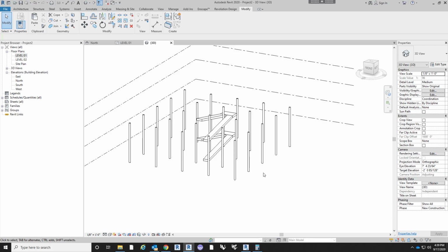If you change the bathroom tile in one, you do not want to have to go in and change all of those 50 times, right? So you just make one group of that unit, you populate it throughout the project, and then if you do want to change the toilet location or a sink or whatnot, all you gotta do is edit the group, hit the check mark, and it'll populate through the entire project.